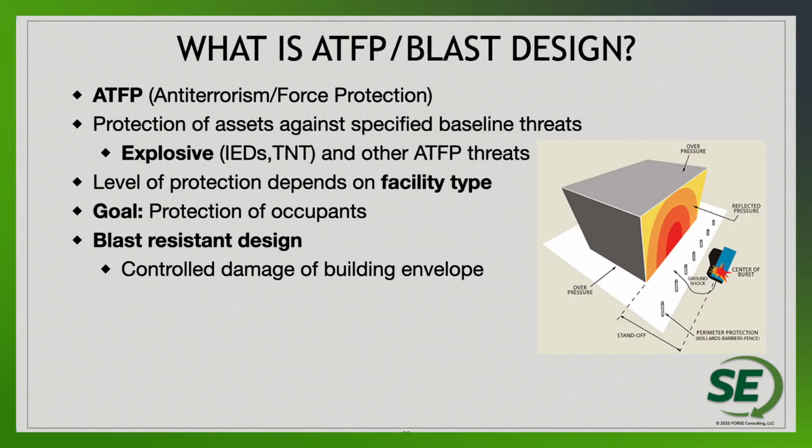Now, looking at ATFP blast design, I mentioned it stands for Anti-Terrorism Force Protection. So it basically just sets the baseline threat for various explosive devices, and it really develops the performance goals we need for our buildings. So we're not really trying to eliminate all the damage. We're trying to first avoid collapse and protect life. But obviously, blast resistant design is focused on controlling damage of the building envelope.